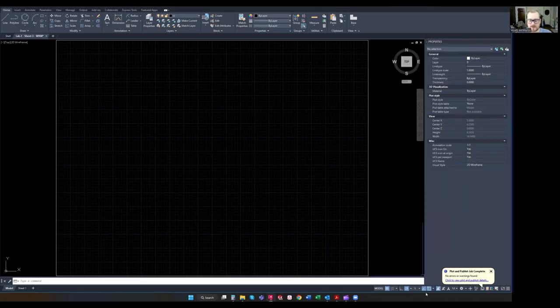All right, so we're going to turn on our grid snap and go ahead and start with a rectangle. Start in this upper right hand corner here, maybe 2 inches over, 1.5 inches down. D enter for dimensions, and that rectangle is going to be 3.5 inches by 2 inches. And then again, you have to snap your quadrant. Go ahead and snap, dragging down and to the right a little bit.